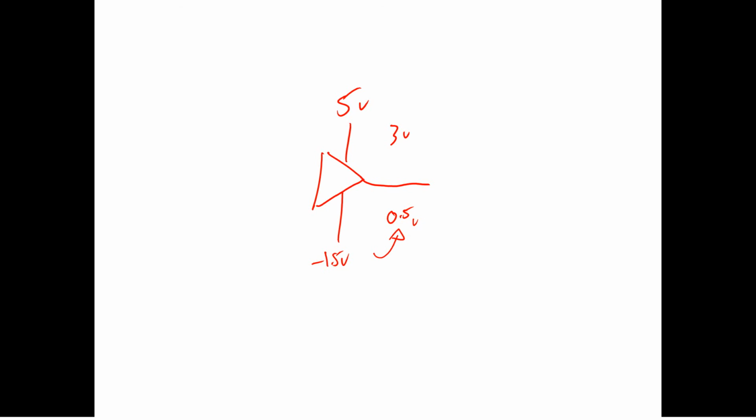And ideally you'd want a higher upper limit. You may be limited by your batteries, but if you could put this up to 6 volts, then you'd have the ability to swing between 0.5 volts and 4 volts. So you'll have to get a little bit creative with how to power the op amps to avoid running into this headroom issue.